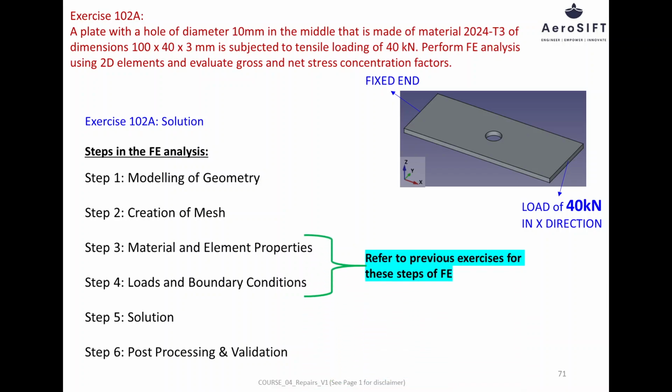Steps like defining material properties, selecting element types, and applying boundary conditions can be referred from earlier exercises as they remain unchanged. The key focus here is on solving the model and interpreting the results to understand how the hole influences stress distribution under tensile loading.